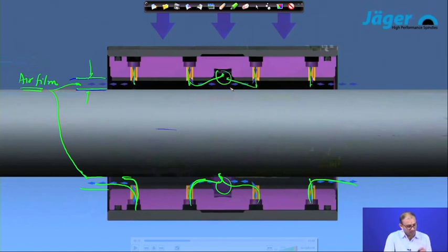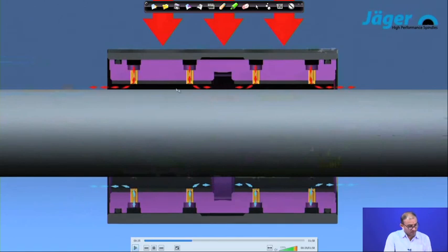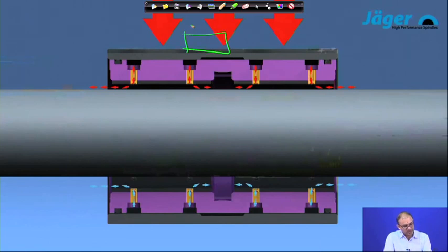So, you do not need to worry about what is going to happen after release of the air, correct. So, now what is going to happen, that now it is in a free motion. After that what we are doing, that we are adding workpiece, we are adding the tool and doing machining and everything. So, your displacement, this whole thing will go down. Because of that, what is happened, that earlier it was balanced force, right, force at this location and this location both were same, but when you are putting this thing down, what is going to happen, that this space available here is less. If the space is less, your pressure is more, and here space is more, so your pressure is less.